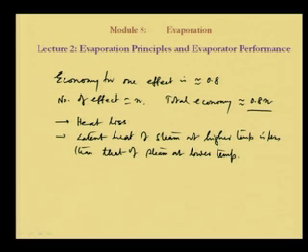So, what is happening in case of evaporator, that steam is put in the shell side, and in the tube side the liquid is there. So, the liquid is being heated. So, the liquid is being boiled. So, the temperature of the steam will be definitely higher than the temperature of the boiling liquid in the tube.